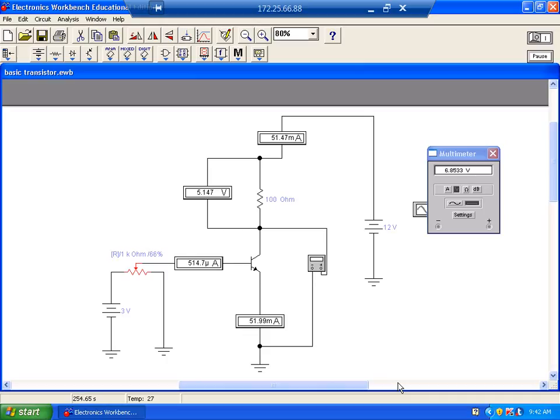And I think if I do one more, I'm going to go over that. Yeah. So that's the best I can do, 619 microamps. But notice my transistor is dropping 5.8 volts, so my resistor is going to be dropping 6.2, right? Or I'm sorry, 4.2.